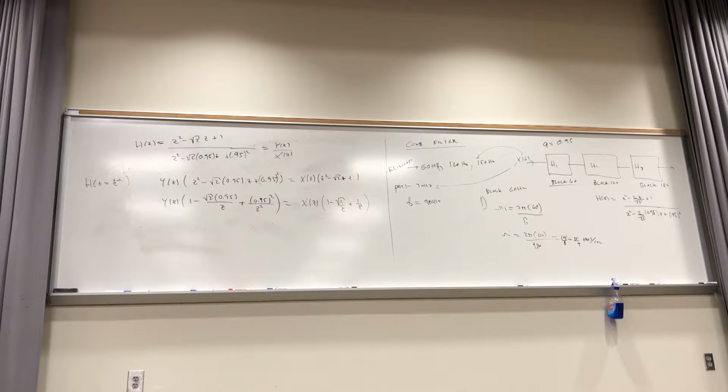Last step: we want this as a difference equation. Remember, a real-time difference equation is easy to implement. You only need a little memory. You keep track of only a few numbers before, x and y, and we predict the next value for y. Do you follow me on this, class? Remember, the clock cycles are really the values of n. Every time you go through a clock period, that would be like incrementing n by 1. Everybody understand this? It should make sense to you how a microcontroller could do this.